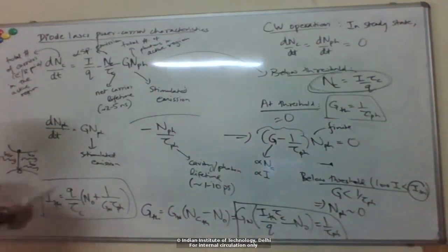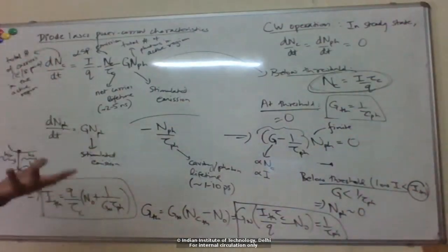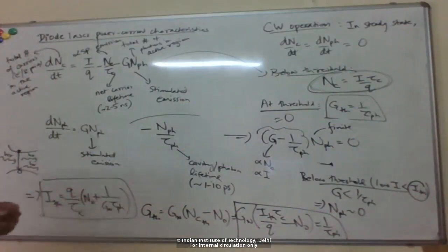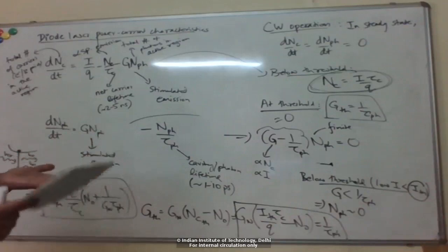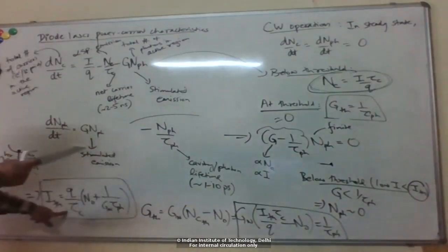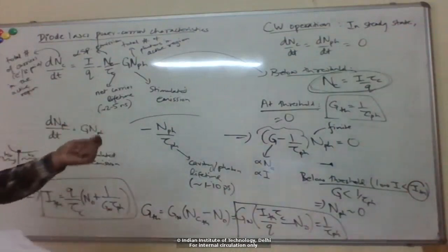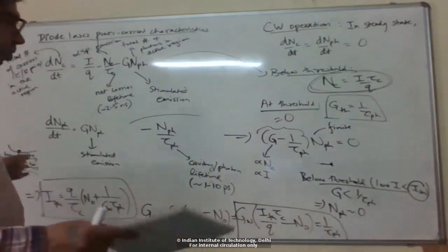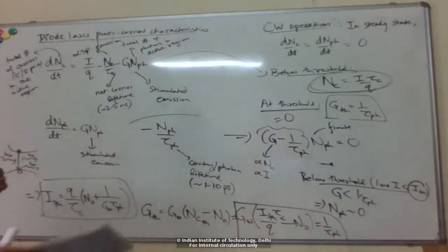Okay, so one thing to note here is typically, like we saw for the LEDs also, as we increase temperature, let's say due to absorption in the defects or some heat being generated in the device, and the temperature of the device increases, that reduces this carrier lifetime. So the carriers now recombine faster, and the non-radiative rates go up due to, again, recombination in defects or some phonon-assisted recombinations.